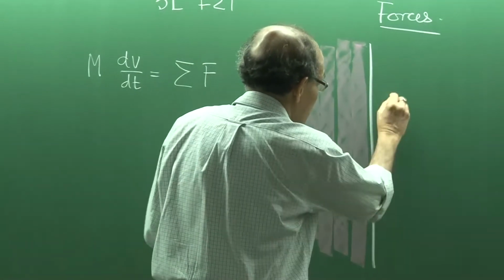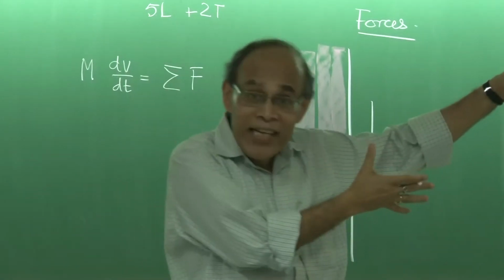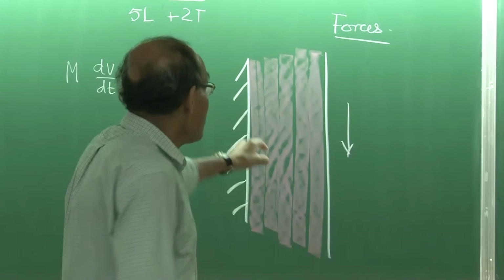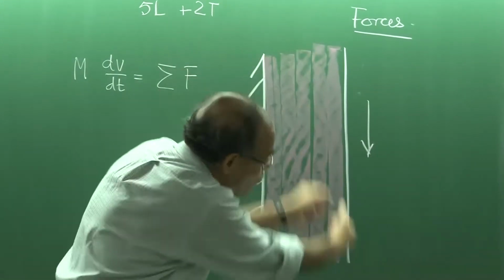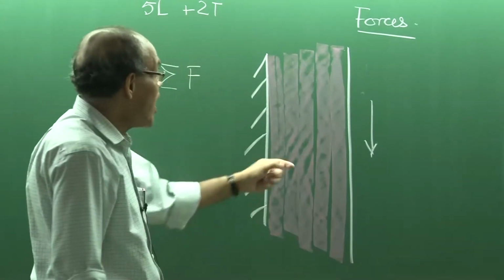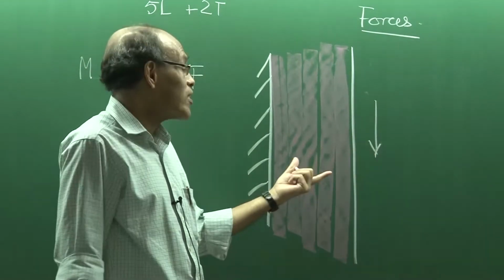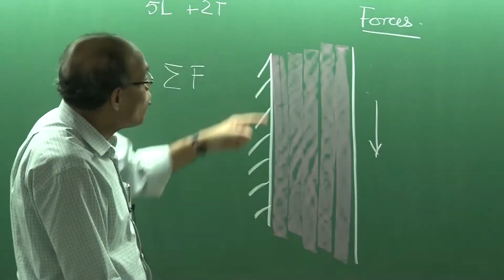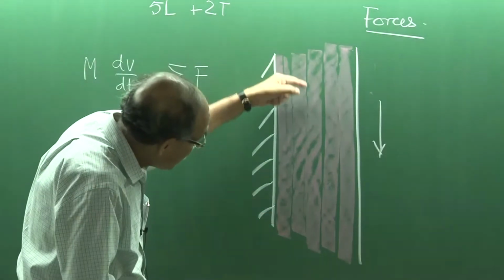is going down. So as you all know, for example, when a train moves, we see that the wind along with the train tends to move. So as the billet or the bloom or the slab moves downwards, it tries to drag the liquid film down, and as a result, it flows downward. This motion induced in the film is because of drag, so we call it a drag-induced motion. Also, because there is a gravitational force acting, we will see that there will be a natural tendency